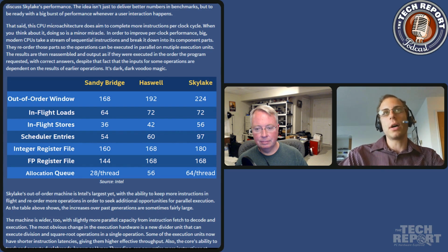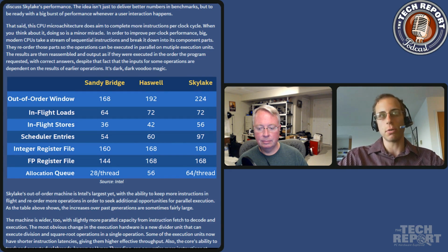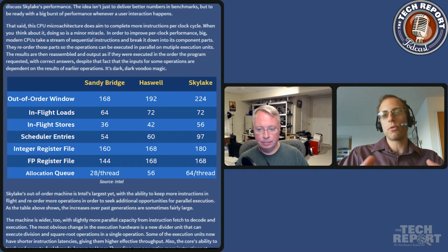So I think what's going on is that there may be a separate scheduler or separate queue or some sort of structure that differentiates between memory UOPs and execution UOPs that just write to registers. And it's also possible that they could be doing some sort of internal bundling where, for example, a bunch of things that are part of one instruction but multiple UOPs end up sitting as one scheduler entry. Right. And because we've seen that type of packing that they've done with related instructions.